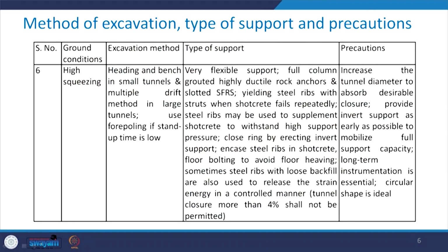Coming to the next ground condition, which is the high squeezing condition. Heading and bench in small tunnels and multiple drift method in large tunnels. Use fore-poling if stand-up time is low.